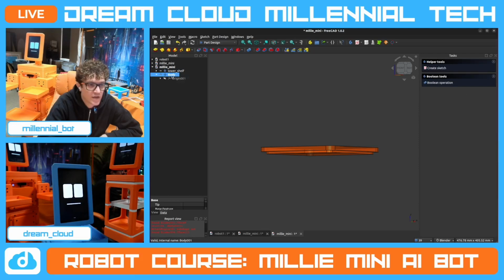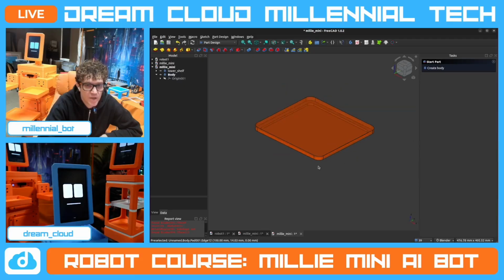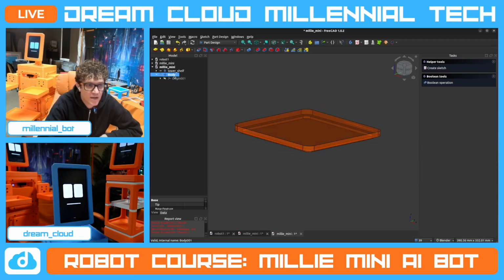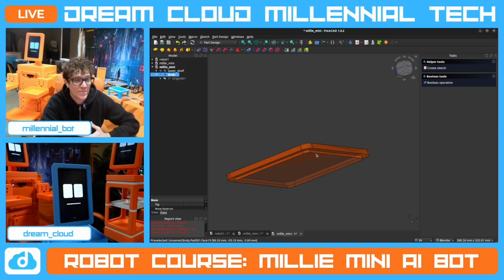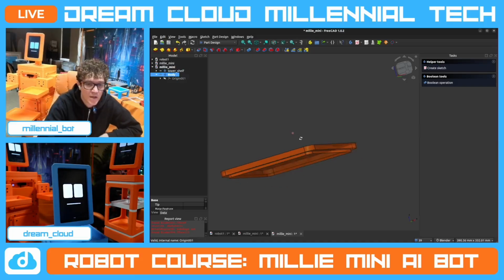It's going to come in over here, right? Now, what I really want to do is create a reference using this initial body, so that I can create this body from that body, right? I don't want to create another random body in space. I actually want to create this body based on this form, because it already has so many things. And I want to create it on that face. So how do I create something on that face without it being part of the same body? How does it become a new body? That's basically what we're solving.